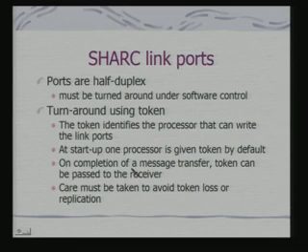On completion of a message transfer, which may involve a sequence of 8 bytes, the token can be passed to the receiver. When the token is received by the receiver, the receiver will change mode and become a transmitter. So, that is how the turn around can be done using the token. Obviously, under such a situation, care must be taken to avoid loss of token or even replication of token.